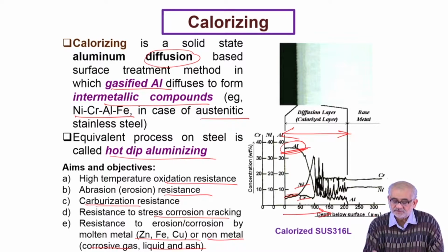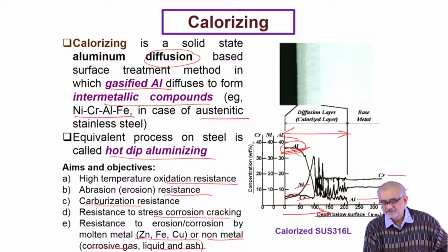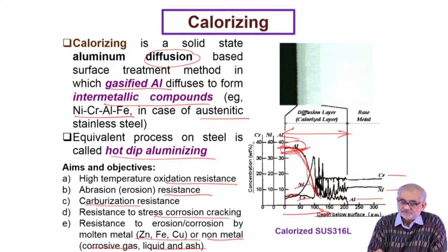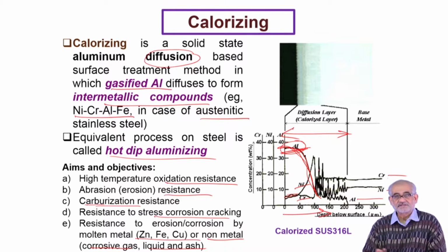We are talking about an alloy which contains all these elements. So this is the base level of chromium and aluminum, base level of aluminum. So there is no aluminum in the substrate or very little aluminum in the substrate, but very high aluminum in the surface. So this diffusion layer is because of the principles of diffusion coating. But still, I must point out that this dip is fairly sharp. So the interface, coating substrate interface, is much sharper than, let's say, carburized layer.